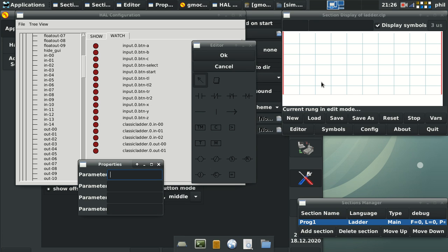It's not going to eliminate contactors, large high voltage relays. Just because you create a circuit that's called lube pump doesn't mean that the PLC is going to physically lubricate your machine. You have to buy the lube pump, but then you can create the timer logic within PLC to control the lube pump via your breakout board output going to a physical relay that would trigger the pump to go on and off.